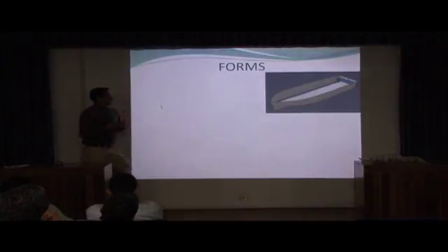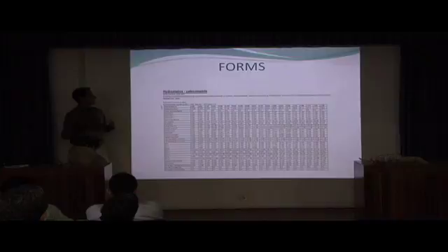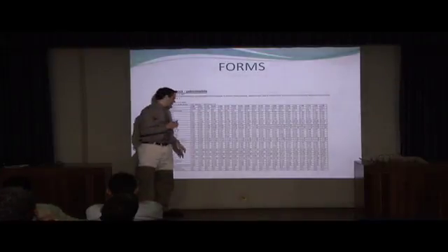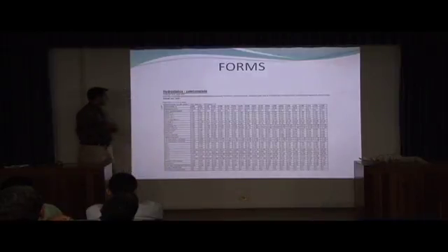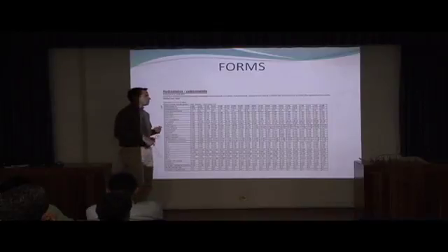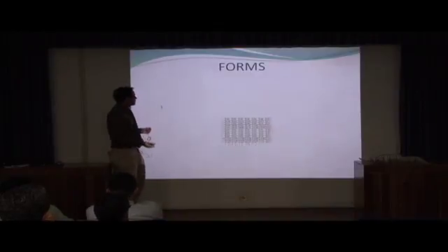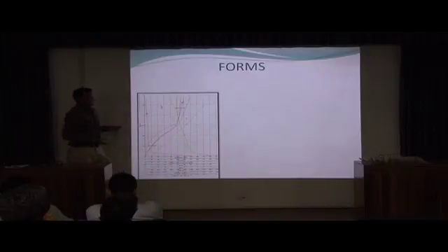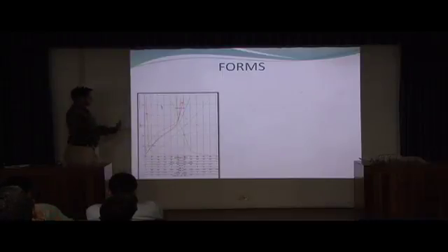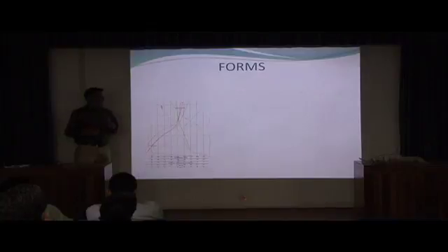And here I have the models, and then the calculation. The calculation is here for the different drafts. So important: the block coefficient, prismatic coefficient, the KB, the KG, and all of the displacements, and all of these calculations for the model to have the construction for the passenger ship. Here I show you the graph for the different drafts with the displacement and all of the calculations that I said before.